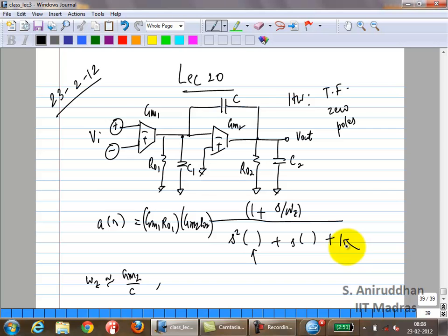No, you gave me the relative, the two pole positions, approximate positions. Are they going to be very close, very far apart, somewhat far apart? Far apart. Because in one case, you have the Miller cap, the other case you don't, right? That's the whole idea. Okay?